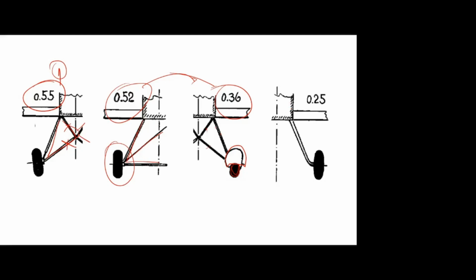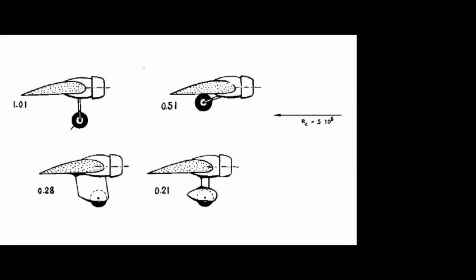And nowadays you see there is only one strut, the landing gear strut. So it is reduced to 0.25. Further, if you give the cowling that is covering this, it may be reduced to 0.15 or something. It will be further reduced. This is another configuration.